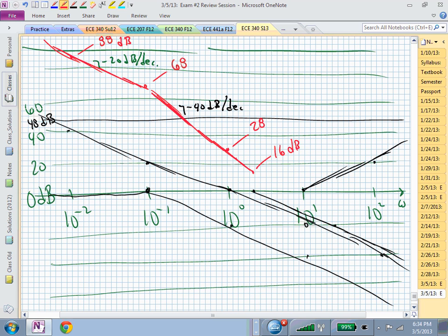Now what happens? Now I have 3 poles active beyond omega equal 2, which means if I didn't have anything beyond 2 at 20, I would be 60 dB down from 16. Is that clear?